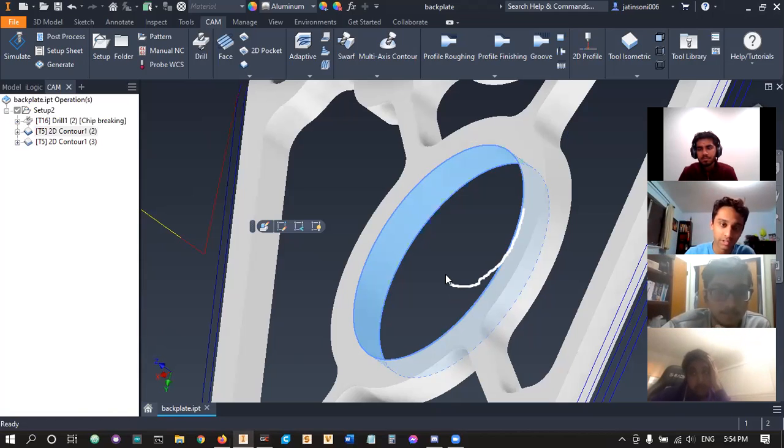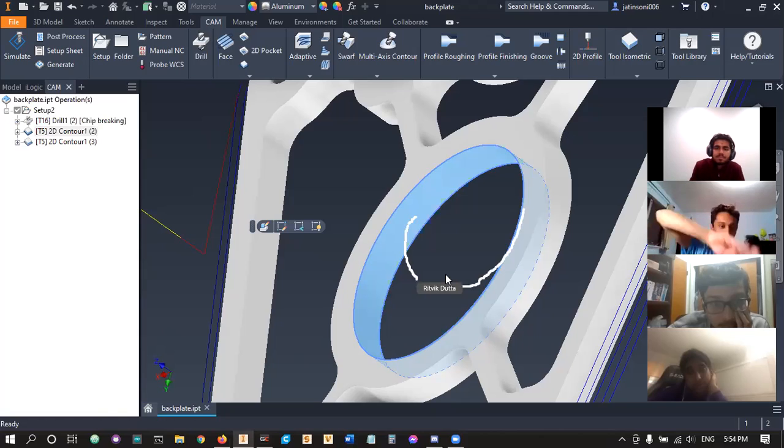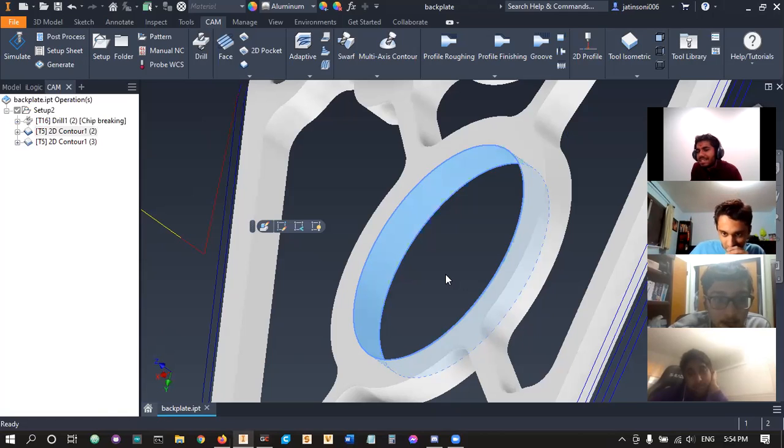And the same thing goes with leading out. If you end over here, you want to end by rolling out. That's the whole point of a lead-in, lead-out. You don't need it. It's just to make it as smooth as possible. It's super nitpicky, so it's not absolutely necessary. You can also think of it as ease in and ease out, where you're easing into your part so that you leave the least amount of visible damage to your part, and you're easing out of it so that there's the least amount of damage.